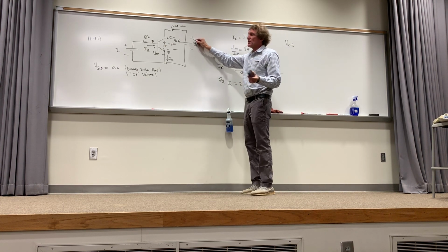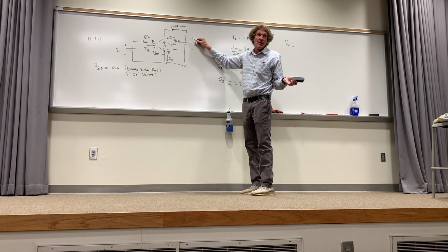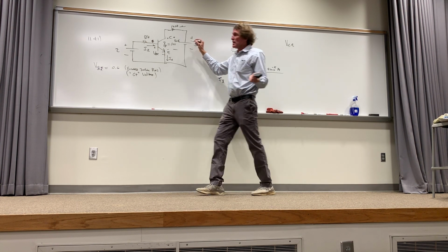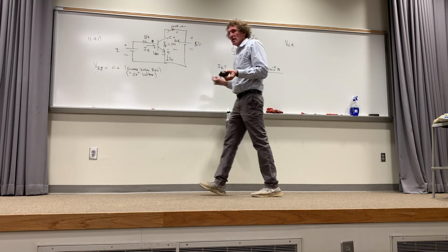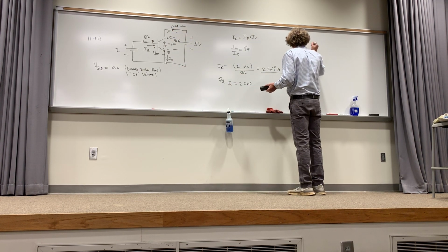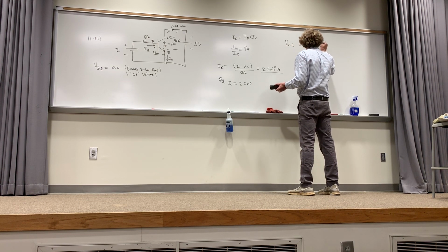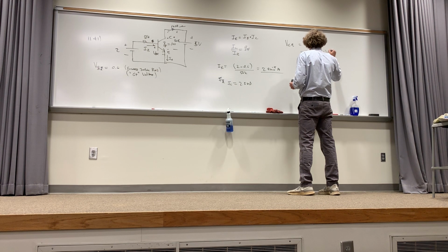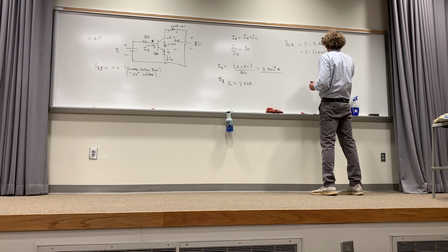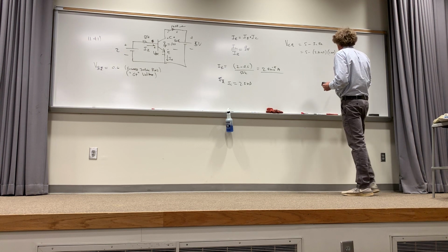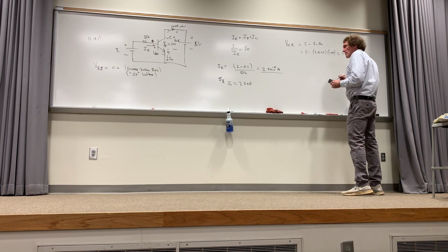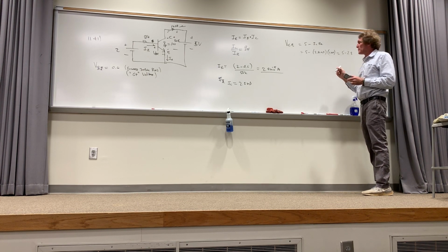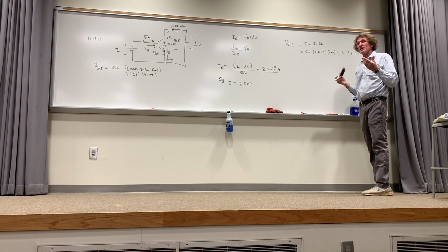Well, what would it be? I have 5 volts here, right? Before it was 5 volts, wasn't it? But what's reducing it? This voltage drop, right? Correct? So VCE would be 5 volts minus IC times RC, that's the resistor termed RC. Or it's really going to be 5 minus 2.8 milliamps times 1,000. Or that's 5 minus 2.8, correct? Or it's 2.2 volts, isn't it, class? You with me on this? You follow me, just a little bit different, right?